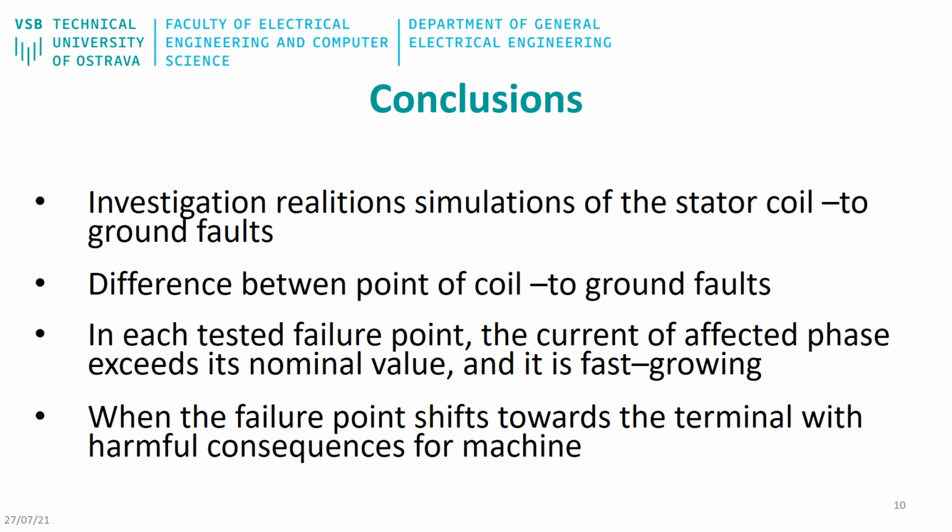In conclusion, I would like to say that our investigation of coil-to-ground motor failures in relation to the fault point is a nice example of the use of finite element method modeling in practice, because there was no need to build any prototypes or make measurements. It was necessary to have a suitably tuned physical model to verify the modeled facts.